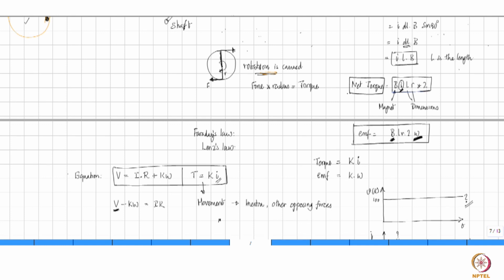But having reached a value of speed that will generate an induced EMF equal to the maximum voltage the machine can withstand, if you now want to go beyond that speed for some reason, usually machines are designed such that the integrity of the mechanical system is valid for much more than the speed at which the induced EMF is equal to the maximum voltage the machine can withstand.